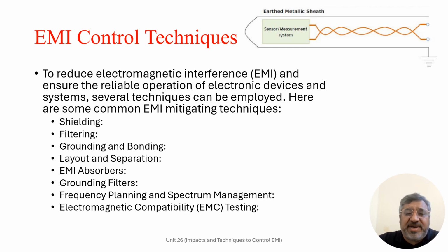minimized. Electromagnetic compatibility testing, or EMC testing, is highly practical for wireless communication design, operation, and maintenance. This is performed to ensure compliance with regulatory standards and assess the susceptibility of the device to EMI. By subjecting the device to a controlled electromagnetic environment and analyzing the performance, potential EMI issues can be identified and addressed during the design and development stage.